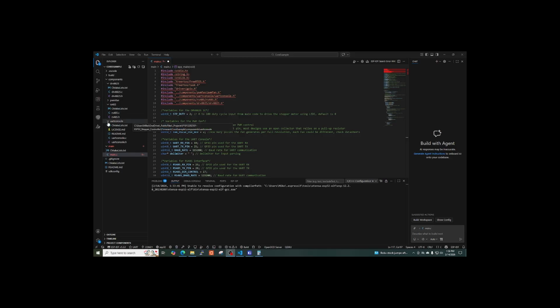So what we might do is go ahead and do that for the status and the cycle count. Because for the cycle count, I want to be able to incorporate non-volatile memory storage. That way it will persist the cycle count through the entirety.